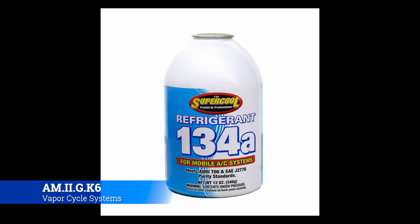Okay, so R134A comes in containers measured by the weight of the refrigerant they hold. Small 12-ounce to 2.5-pound cans are common for adding refrigerant. Larger 30 and 50-pound cylinders equipped with shutoff valves are often used to charge an evacuated system, and they're used in shops that service vapor cycle systems frequently. So basically, the shops that do this kind of thing will have very large 134A reservoirs to service from. Everybody else just kind of gets these little cans to do any kind of one-off servicing that they end up having to do. Larger cylinders are also used in full servicing carts we've seen before.